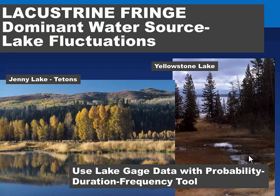And in some extreme cases, large lakes will set up lake seiches, which are basically long-term wind that will raise the elevation along one certain shoreline of the lake, and those lake seiches themselves can raise the water level in those lacustrine wetlands. So the hydrology analysis of water movement in those wetlands can be done with lake gauge data, and you can actually even perform the same probability, duration, frequency analysis with that data as with stream gauge data.